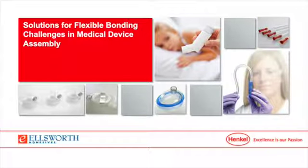Okay, and this looks to be our final question, and this is going to go to Dee. How quickly does the output of a typical LED cure system decline? Thanks, Molly. Degradation for the LED system is very slow and very gradual. As an example, if we look at 20,000 hours, we would still expect more than 70% output to be present. If you contrast that with your UV bulb system, which typically requires replacement at 2,000 hours, it's a significant cost savings in terms of replacement bulbs.